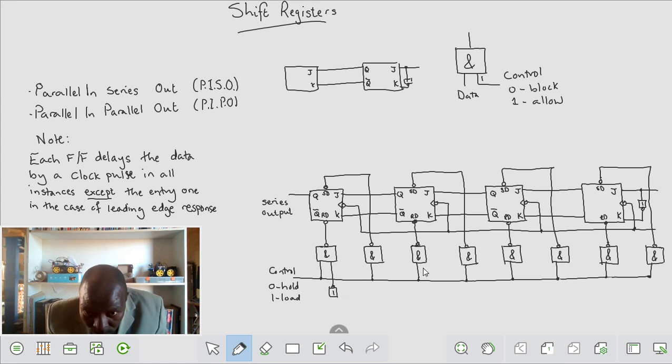But for all that go to the reset, I need them to go through an inverter, because a 0 then needs to be a 1 here. At 1 and 1, this gate will give us 0, with 1s only. So I need 0s here to be changed to 1s for the reset line, not for the set line.